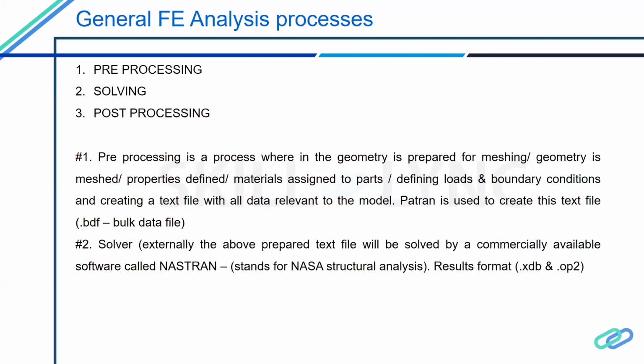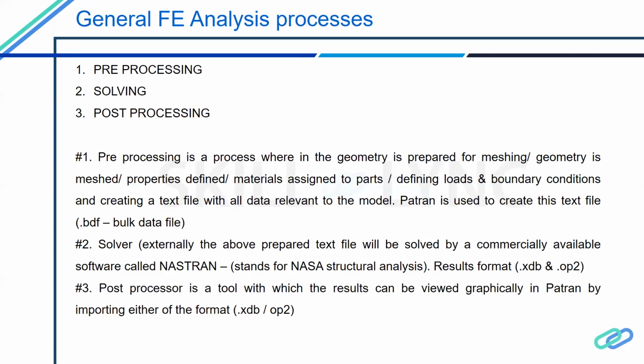The second step is solving, and this PATRAN BDF can be solved using the NASTRAN solver, and the results come in XDB or OP2 format. And again, post-processing is seeing the results that you're willing to see. These results can be viewed graphically in PATRAN by importing the XDB or OP2 file, and you'll be able to see where the max deflection is, where the location of max stress is, and everything.